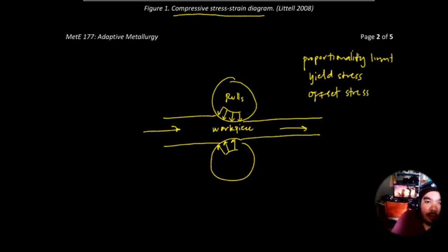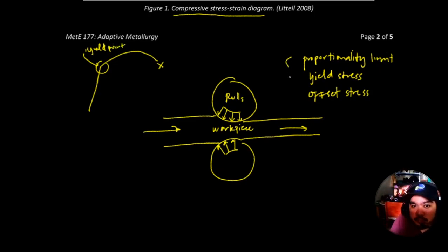So in most cases, when the metal displays something like, say we have a graph like this, this is a typical UTS graph. If you look at the typical tensile graph, in most cases for metals like steel, at this part there is a stark contrast between your plastic region and the elastic region. So this point is what we call the yield point, and all of these three exist as one point. They are just called the yield point.